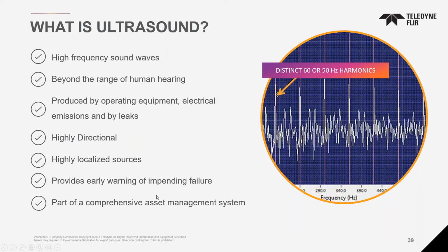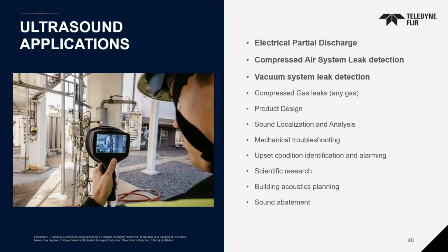Remember, I told you in the beginning of the curve, the P-F curve of the condition monitoring or the failure, that ultrasound can be a very early warning system to detect starting points. So it gives you time to react or plan out your repairs or shutdowns and all that. You don't have to be surprised, because unplanned is very costly. So it can really add a lot of cost savings to your program.